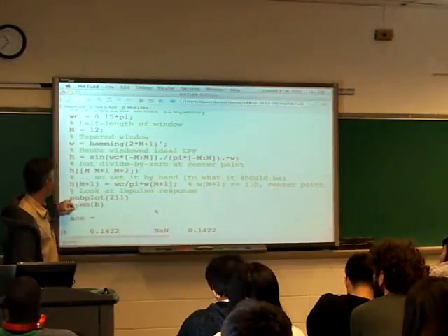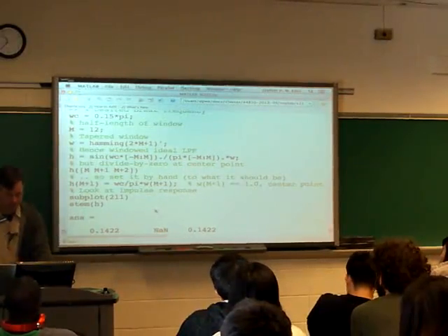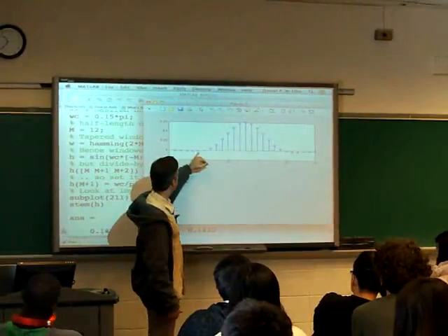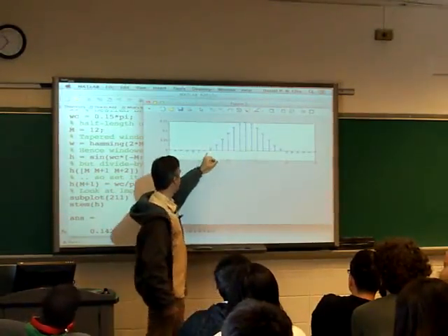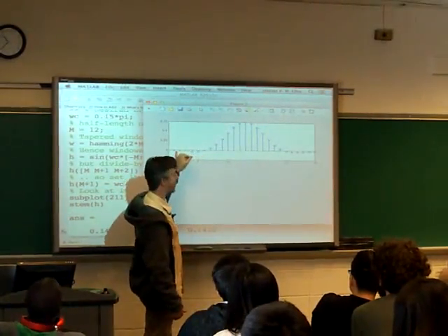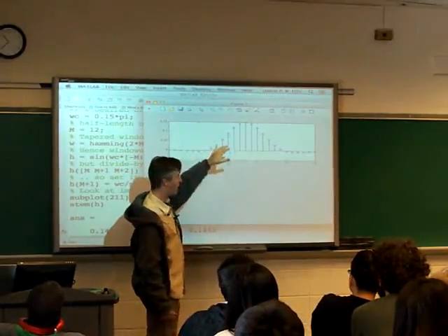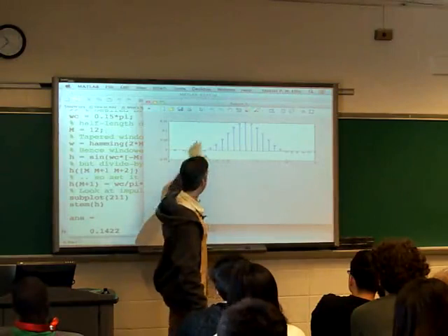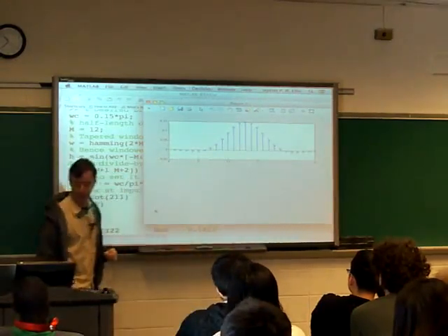So we've manually set that, and then we can look at the result. And here it is. That's the thing we had plotted. You know, it sort of wants to be a sinc function, but by the time we get to the edge, the window function, the Hamming function, has attenuated these bits quite a lot, so it gets squashed out quite a bit at the edges there.